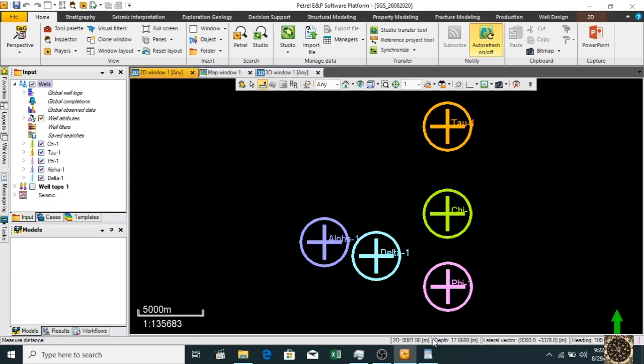Okay, let's uncheck that. There is a set the domain option. There are 2 options, 3 options, any. It will show both time and depth domain. If we want to see only the depth domain, we can select TVD. It will only show us the depth data. And if we set TWT, the two-way time, it only gives us the data which is in the time domain.